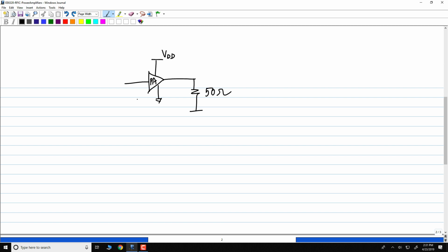So you want to put out power, but the number one thing is output power, and number two is also gain. The circuit should also put out gain for various reasons. Obviously the PA is going to be somewhat nonlinear. Now, if the PA does not have a lot of gain, even the previous circuits will also be in the nonlinear regions. That is not necessarily the best, right? So you would prefer the PA to have some gain.